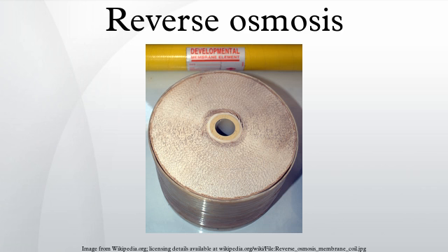Disinfection: post-treatment consists of preparing the water for distribution after filtration. Reverse osmosis is an effective barrier to pathogens, but post-treatment provides secondary protection against compromised membranes and downstream problems. Disinfection by means of UV lamps may be employed to sterilize pathogens which bypass the reverse osmosis process. Chlorination or chloramination protects against pathogens which may have lodged in the distribution system downstream, such as from new construction, backwash, compromised pipes, etc.